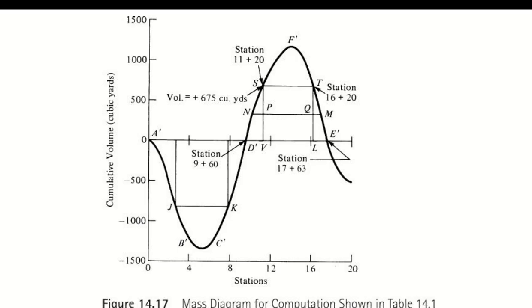Okay? Clear? Can we request? Which one? All things in place. Okay. Can we request? Which one? This one. 11 is per cubic yard per station. I'll take 11, multiply by the material, multiply by the number of stations. Okay? The material from the graph. Stations, we did this to calculate the stations. Okay? Now your problem must be here, right?